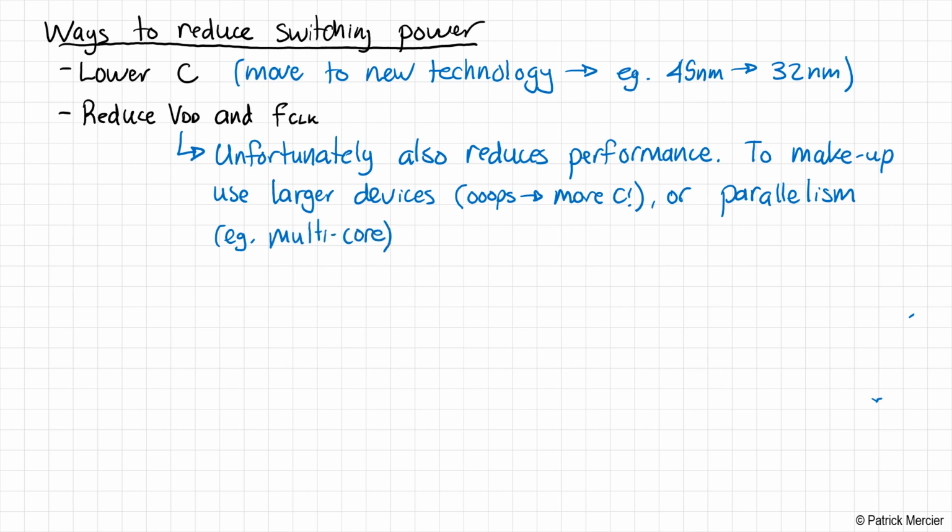So this was largely the solution that the semiconductor industry used when they were hitting their performance limits, for example, with the Intel Pentium 4 processors. They were trying to clock them so fast that the power density was getting so high that it was just unacceptable. And so in order to further improve computing performance, they decided to slow things down a little bit, but put in multiple cores to do processing at the same time and spread out the heat dissipation. So parallelism does help. I should also mention here that parallelism doesn't come for free. We are putting more devices there, so it also does require more capacitance. So there's no total free lunch here, but in the end, it turns out to be a worthwhile trade-off.